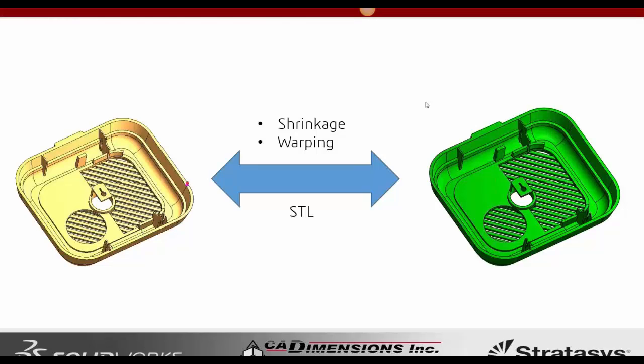Now, if you choose not to use SolidWorks to create an anti-warp part, that STL file superimposed with the original file will still give you a really good idea of how your part is warping, and that can also help you streamline your plastic part design.